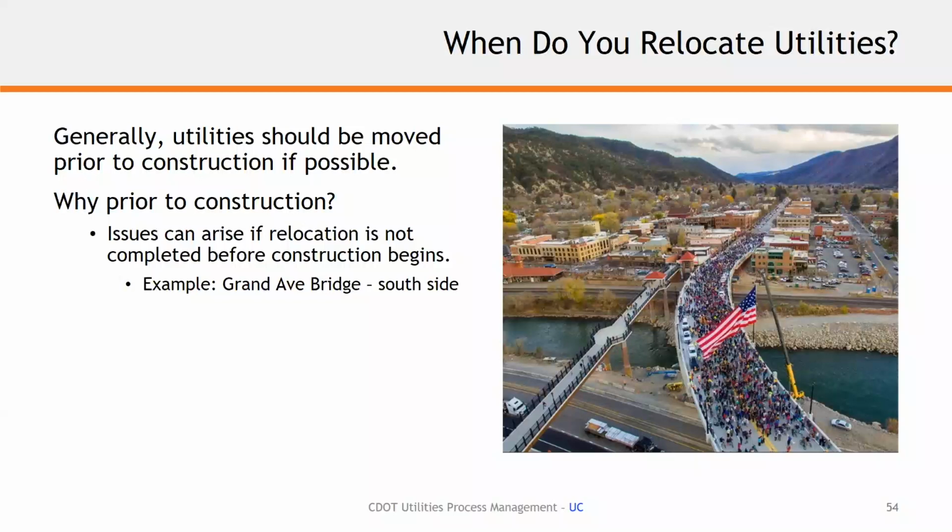And you've got a documented record of how many times you've connected with a utility company in the past. Hopefully you've got agendas and follow-up notes and minutes from the meetings, what was discussed. So you can approach them at the end of the project or right when you're into your design phase, right where you're going to construct, and say, we're ready for you to move. This shouldn't be a surprise to you. So all those building blocks to utility coordination culminate in getting things moved and out of your way.